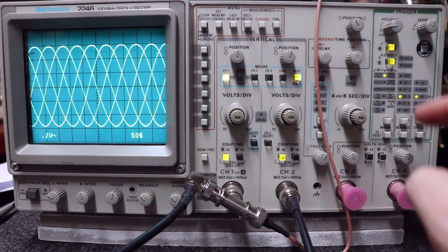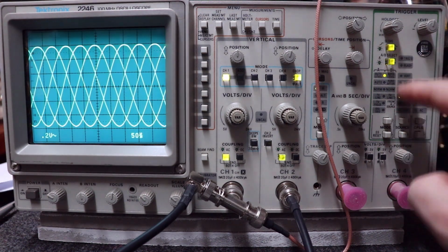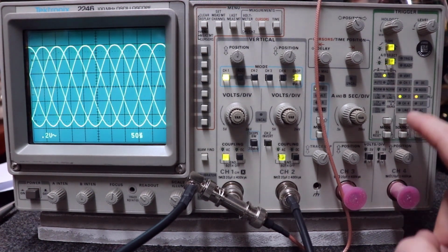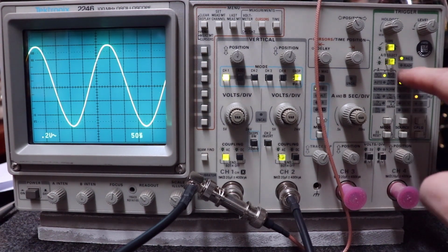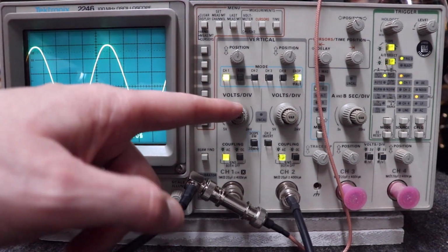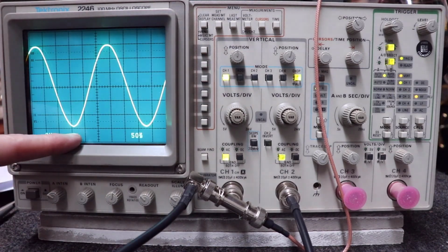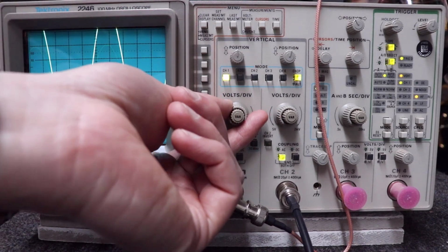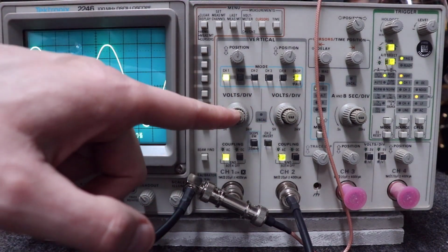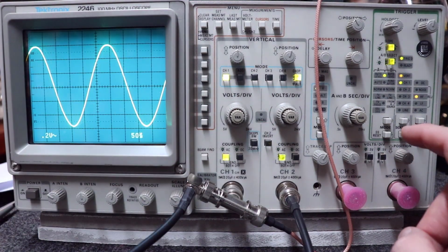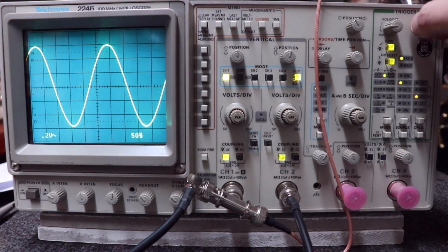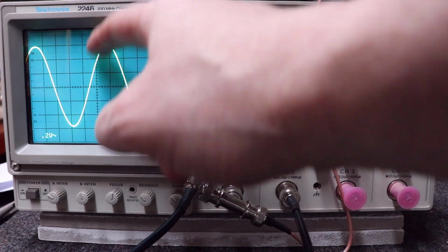Well, this little whole section right here is based on what you want to trigger on. If I put it up here, I'm triggering on vertical on channel 1. In other words, whatever this setting is on is what I'm triggering to. If it's on 1 volt here, I'm triggering based upon whatever settings are on this. If I go down to just channel 1, then I have to pick the level of what I'm triggering on